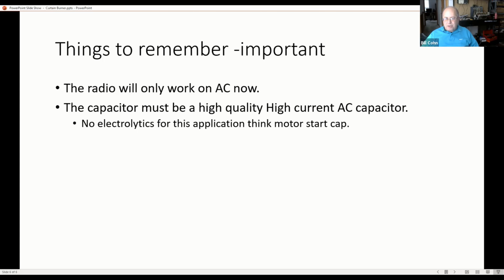I know there are other radios out there that have different tube complements. Some of the cadets may have only had a few tubes. You can also use this capacitor to replace a ballast tube. It will work certainly there as well. There are other techniques, and I'm not going to go into it here, where people have actually put a diode in series with the filaments, which also works, but it gets even more complicated to measure the voltage across the tubes at that point, because now you're not measuring,